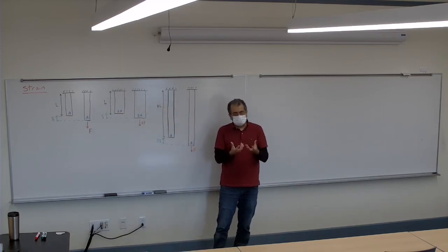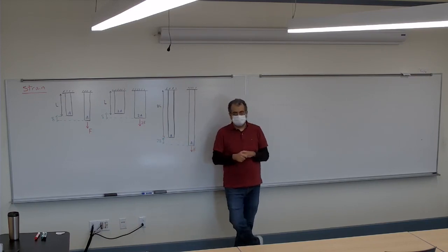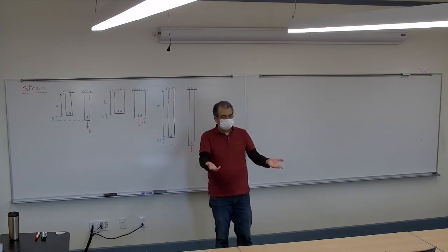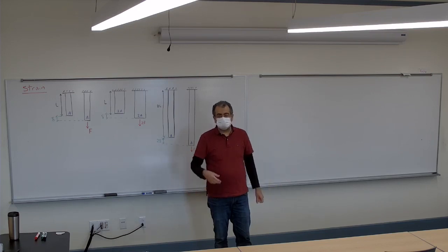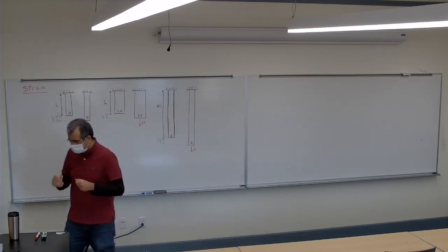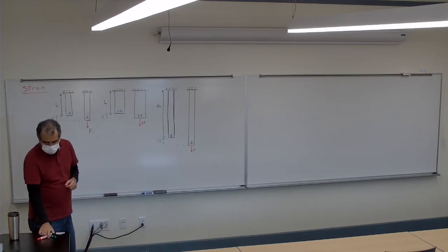But how can I make it more sensible, independent of the length? If I want to say, okay, what's the deformation of the steel? Someone will say, okay, what's your length? But if I want to get something that is independent of the length, so you ask me what's the deformation of steel, I tell you, that's how much the steel will deform in general, under a certain force.